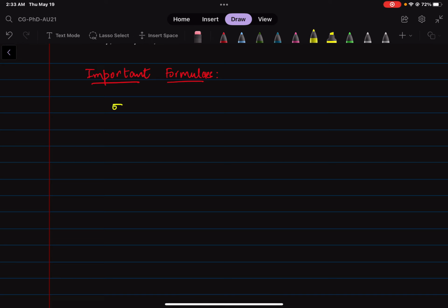So, some important numbers, you have sigma m, you have k subscript t, you have sigma c, you have k subscript 1c, where 1 is the Roman numeral. The sigma m is equal to 2 times sigma naught into a over rho t whole to the power half.